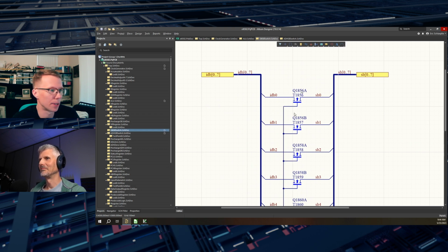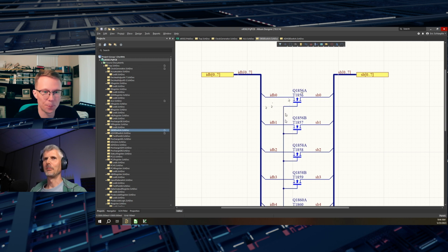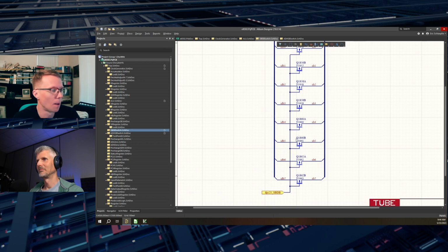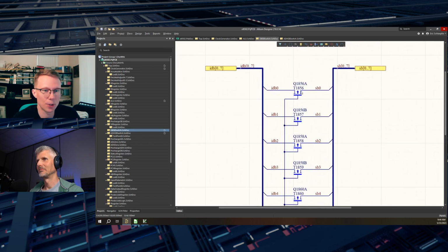And what that means is that they're inherently bidirectional devices, and they also don't have a parasitic diode that affects the channel connections. There are still parasitic diodes that go from the substrate to each channel connection, but because we haven't tied one of the channels to the substrate, we don't get that traditional diode that you would see in a discrete N-channel MOSFET. And the 3-pin package. And the 3-pin package, exactly. And so that winds up being quite important. This one right here is driven by a control line. All the gates are connected together. And so obviously we need enough voltage that we can get this to turn on.